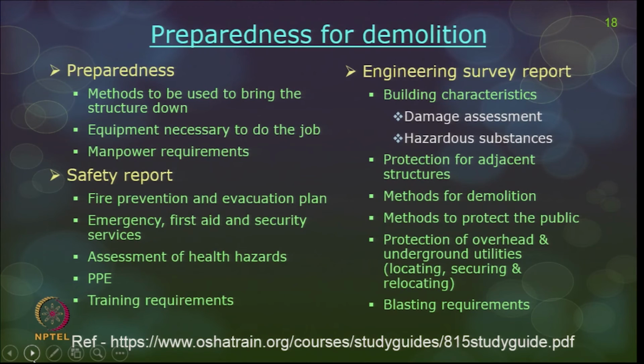Assessment of health hazards in terms of toxic chemicals, or even if it is a concrete structure, the dust coming out of cement breaking and so on has to be thoroughly analyzed. PPE has to be recommended to the workers, and the mandatory PPE has to be worn, and training requirements have to be given to the workers in order to do the demolition.